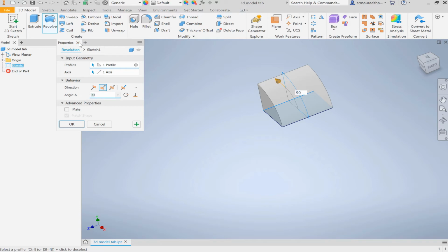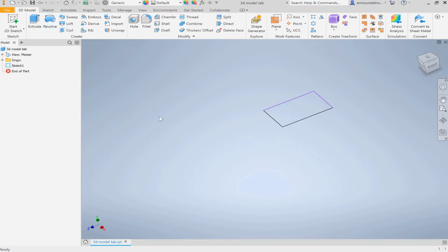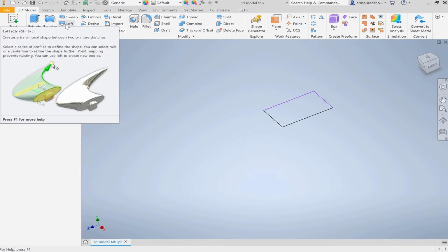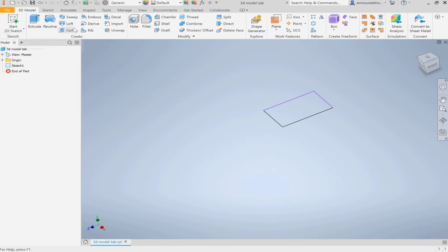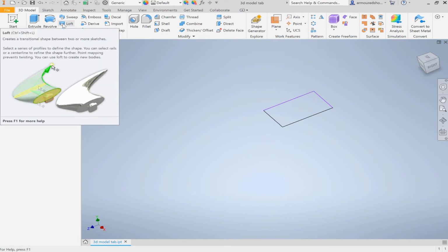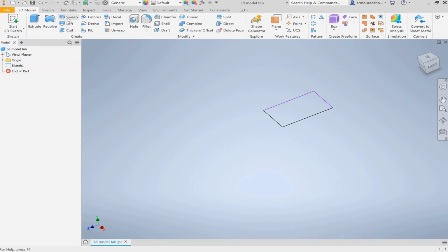So those are your two big ones that you're going to use all the time when going from 2D to 3D. Some of these you'll use, like Loft will allow you to smoothly join two shapes, like you see how it goes from a square to a circle here. It'll just create a transition, and it's pretty nice. Like, yeah, and it'll explain it.